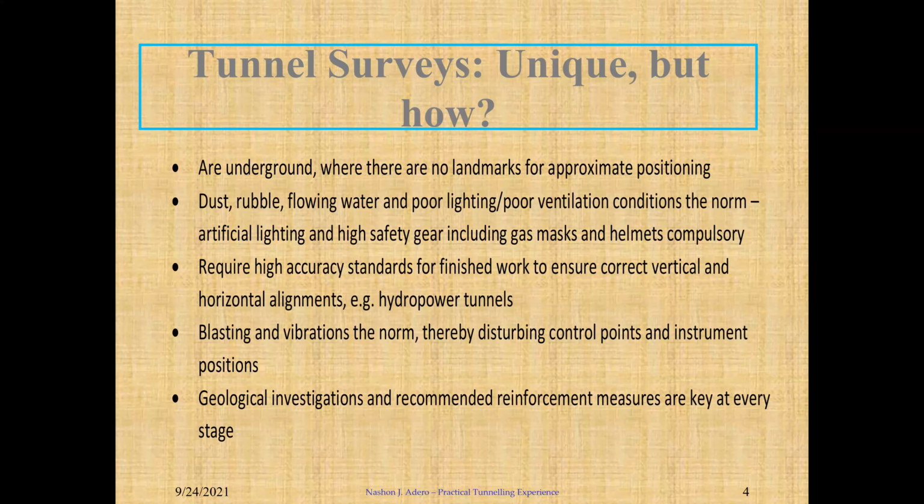They require high accuracy standards for final finishing works, when you are now setting out the invert levels for the concrete, based on a formwork that you have aligned as a surveyor both horizontally and vertically. Blasting and vibrations were the norm when we are talking of these underground works in a tunnel. And this brings us to control points and instrument position.